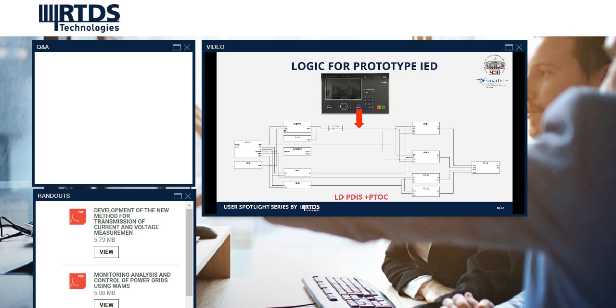The RMSU logical node is designed for calculation of RMS values based on the application of the Fourier filter. Logical node SVTR is designed to check the integrity of the voltage circuit.